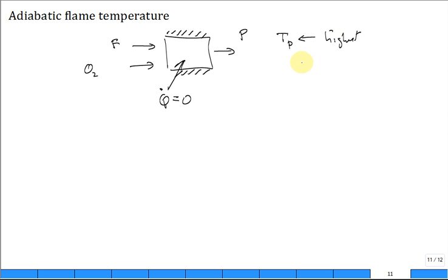All right. And so they talk about the adiabatic flame temperature being that highest possible temperature of the products. Typically you have this 25°C for the reactants. You don't play around with, oh, if I bring it in a little warmer, well, yeah, it's going to be a little warmer going out. But it's dictated by that heat release, how much energy is released per kilogram of the fuel.